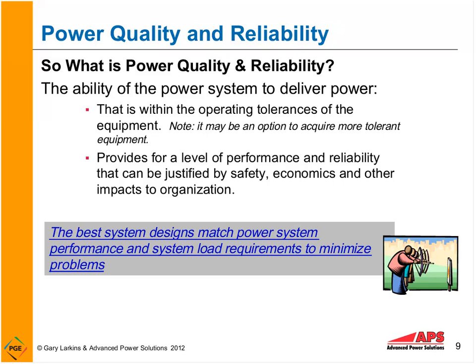Let's say maybe I have a backup generator in my facility, and when I start my drives or start my motors, I cause interference with the way the generator feeds other loads. So this is something we're looking at, compatibility between systems.